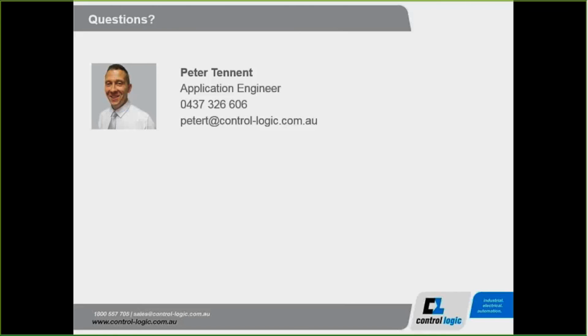You'd have 3 tiers. So each tier is 600 wide, so approximately 1800 long, I think 600 deep, depending on the IP rating, top or bottom entry, you're around about 2200 high. So approximately 1800 wide by 2200 high by 600 deep.